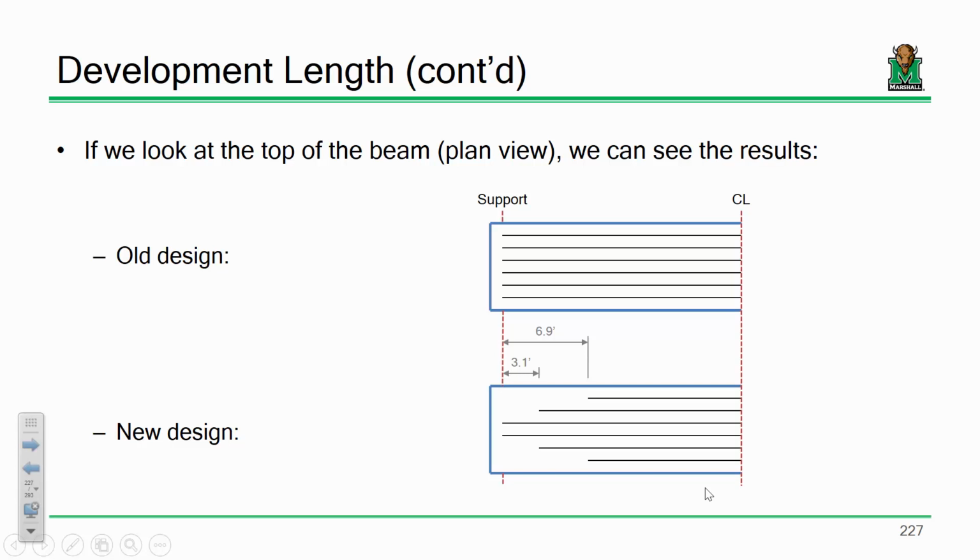Maybe I could trim it up a bit, make the beam a little more lean, and only use the reinforcement where I need it. Only use the 6 bars where the moments are really, really high, whereas where the moments are really, really low near the support, I only use, say, 2. Does that concept kind of make sense?